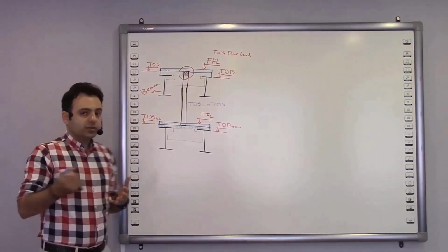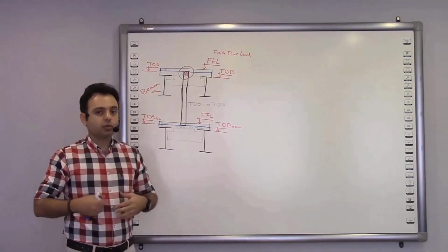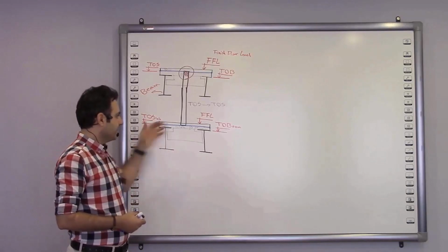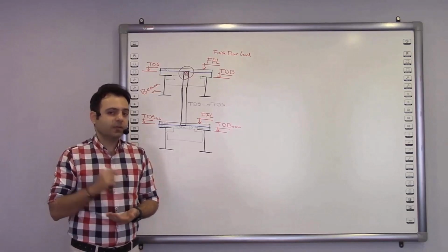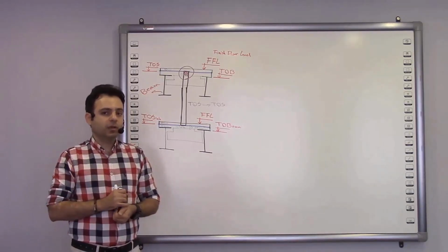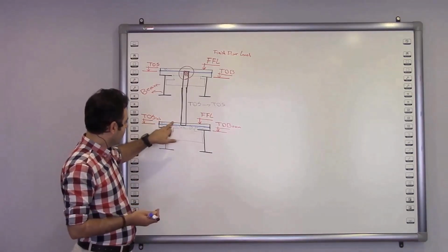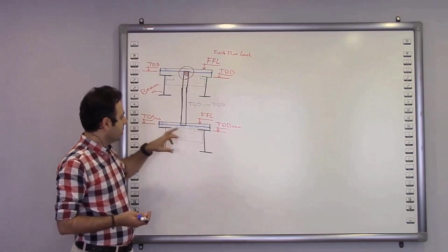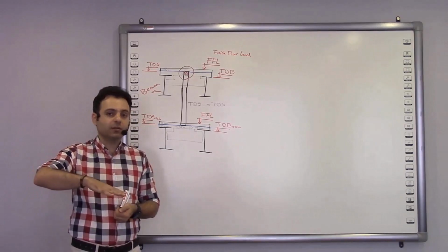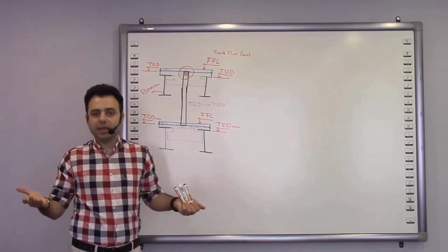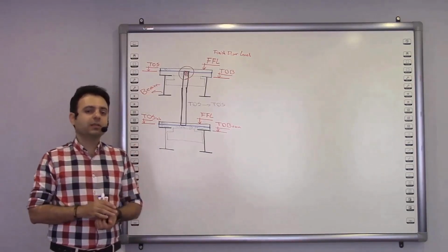Well, you might think that if we start our job with the TOS, then how can we use this FFL here? Or how can it be useful for us? What objects do we have that work only with FFL level? Can you say it? I mean the objects that are on this level. Well, the wall did not start from this level, it started from TOS. Now, what objects work with FFL? Exactly, like for example furniture. All our furnitures work with FFL.